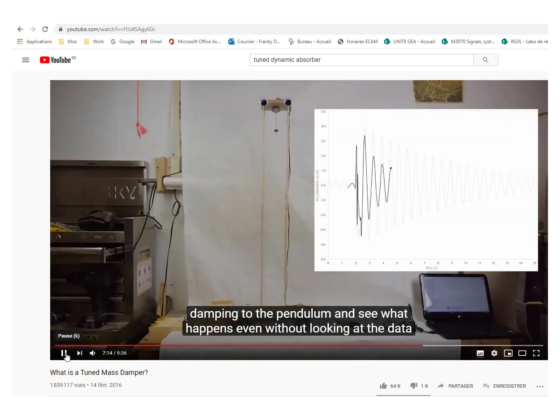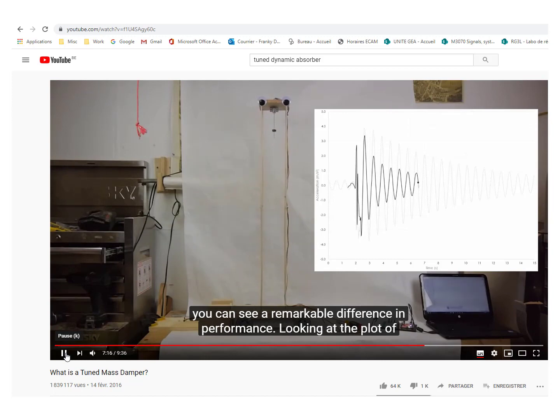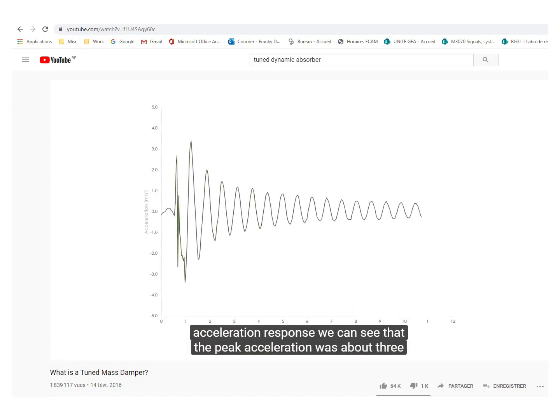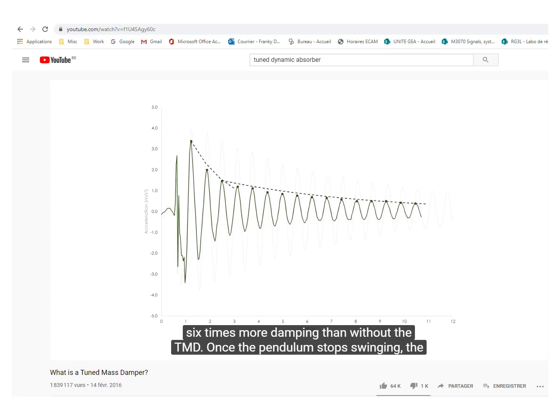Even without looking at the data, you can see a remarkable difference in performance. Looking at the plot of acceleration response, we can see that the peak acceleration was about 3.5 meters per square second, so a reduction of only about 12%. But the big difference is how quickly the motion decays. At the beginning, when the pendulum is swinging, I calculated a damping ratio of over 0.6. That's about 6 times more damping than without the TMD.